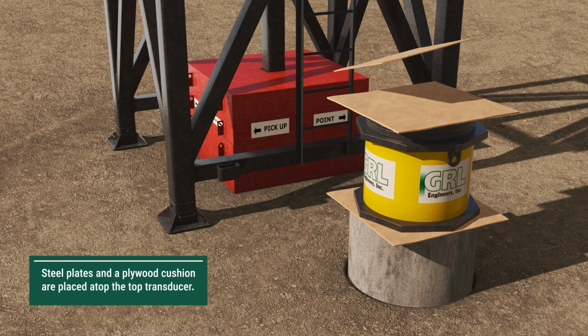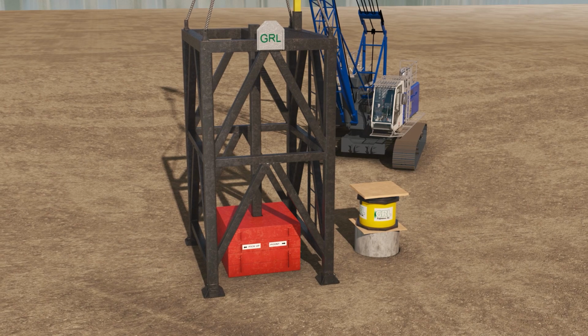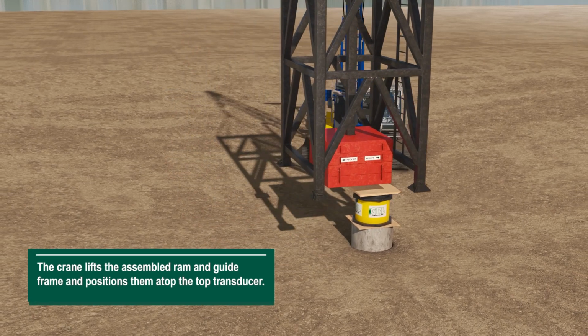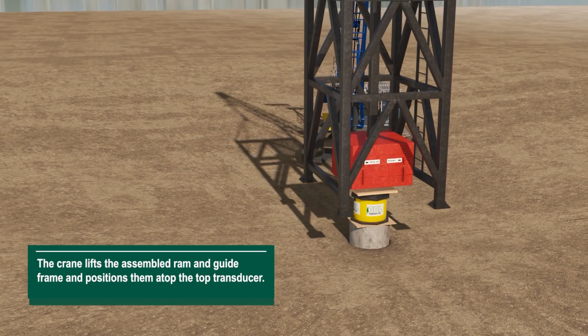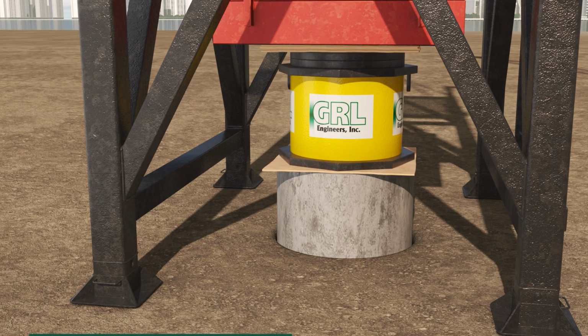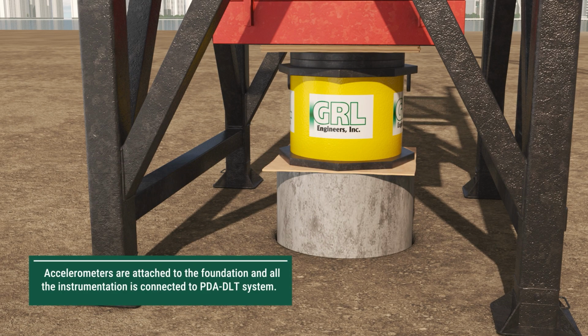Steel plates and a plywood cushion are placed atop the top transducer. The crane lifts the assembled ram and guide frame and positions them atop the top transducer. Accelerometers are attached to the foundation, and all the instrumentation is connected to a pile driving analyzer using DLT software.